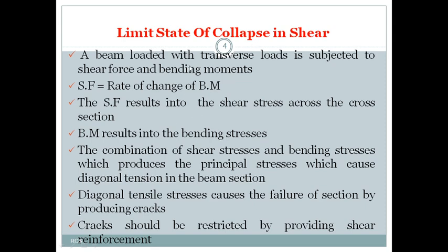Say a beam loaded with a transverse load is subjected to shear force and bending moments. As I said, when a load is applied, a deformable body may deform in any shape. Majorly, it will deform with respect to bending and shear force. We know, based on the concepts of strength of materials, that the rate of change of bending moment is equal to shear force.